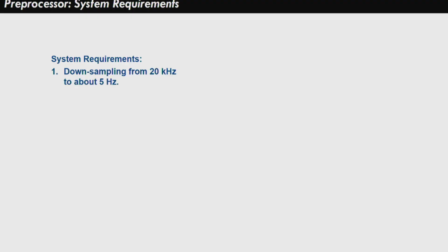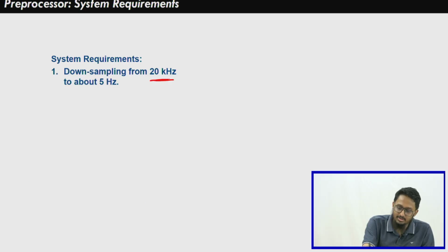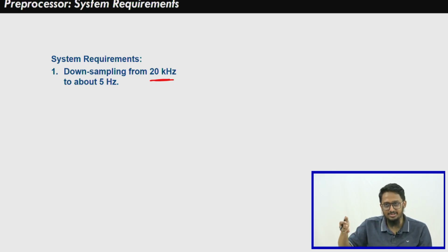Generally, when we are observing signals in the computer, we are converting analog signals into digital signals. This pH is also an analog signal, and generally when we do the sampling, we do it at a very high sampling rate, 10 kilohertz or 20 kilohertz, depending upon the bandwidth of the signal. There is something called the Nyquist criteria, that your sampling frequency should be at least twice the signal frequency. So, generally we want to satisfy the Nyquist criteria, and we sample at a very high rate.